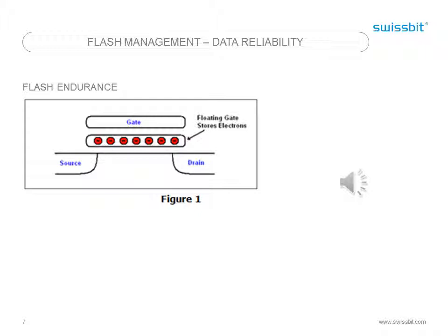The key factor in the design differences between MLC and SLC NAND flash is the controlling write and read circuitry for all cell locations. Because of the increased VT range for valid states between a 0 and 1 for SLC operation, the endurance and data retention increases significantly. Specifically, this occurs as follows.